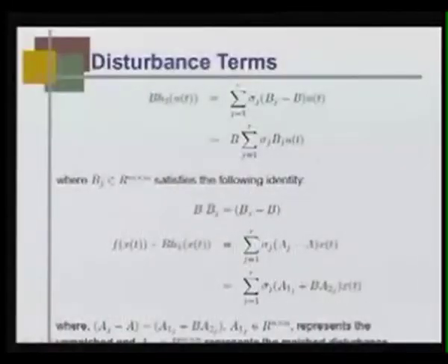That means, if I am designing my controller for the worst case, naturally the controller also will be stable for the other cases. So, the robust control design principle is to design the controller for the worst case. Okay. So, that is why what we will do now is represent this disturbance term a little more elaborately and define the upper bound.